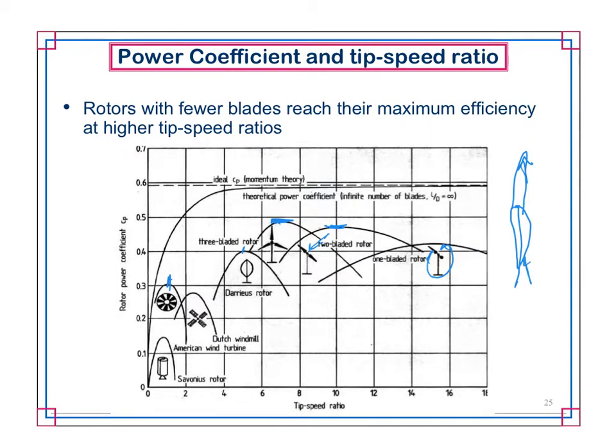And so what would happen is if you were to look at a profile view, if you just use 2 blades, your forces with a lot of wind would be tipping the nacelle in that direction because of the massive amount of force that's being applied to the tip. So with a 3-blade design, you have 2 forces to balance out the maximum force that you have there.